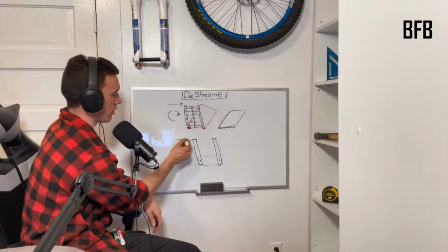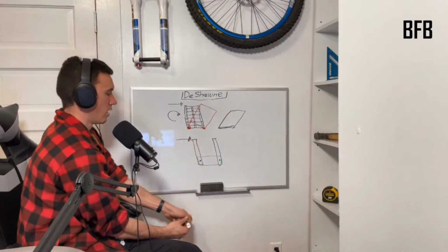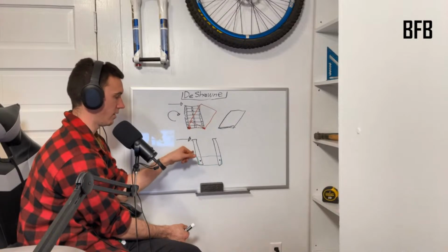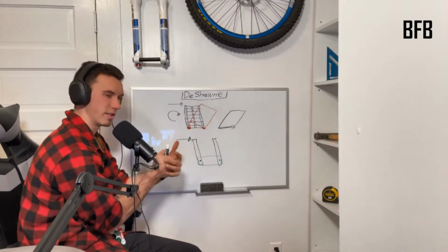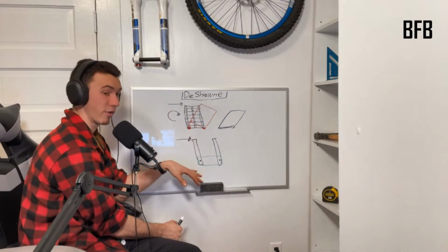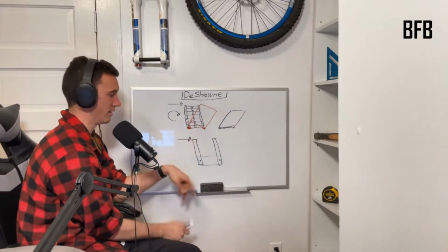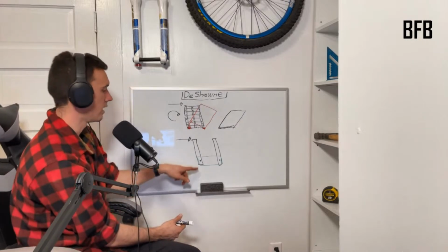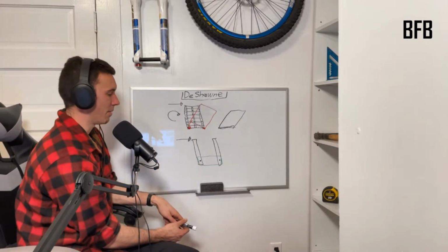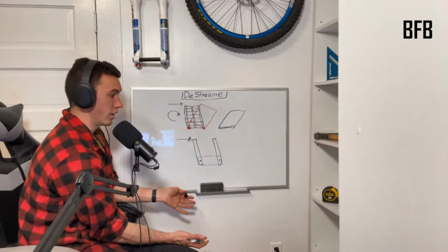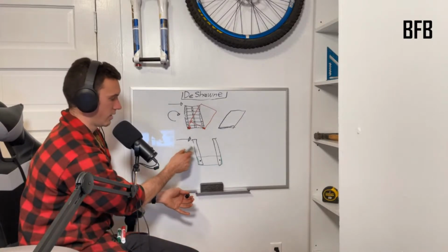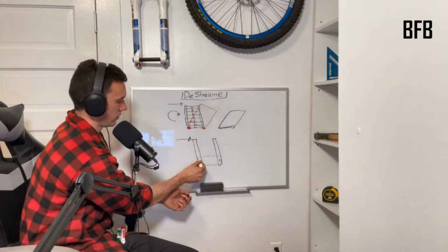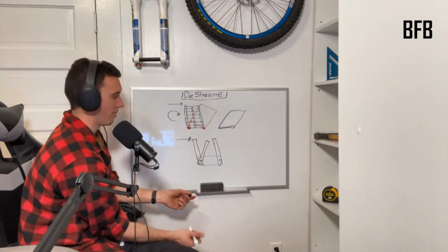If somebody were to come over here and push on this, presuming there's no friction between the plank and the board, neglecting friction, so the friction's not going to resist the twist. Like this is a Teflon plank, and these are Teflon joists. They slide very easily past each other. You put one screw in here, what's going to happen? Well, it's going to pivot because nothing's resisting this. All you've done is you've taken a stick and a pivot point, and it's just going to rotate about that point, and so is the other one.